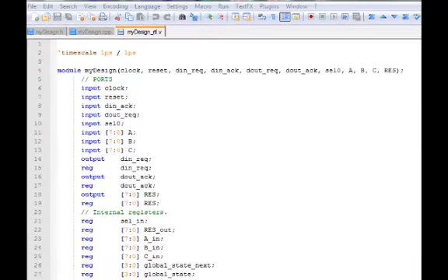So let's take a look at the Verilog code we might write to implement our tiny example. For the moment, let's restrict our focus to the definition of the module itself, as well as the ports and internal variables. Here we see the Verilog keyword module, followed by the user-defined name of the module. In the parentheses, we have a list of all the port names. Next, we see a list of the port definitions. Each one includes the direction of the port, the name of the port, and optionally, some specification of the width of the port. The internal variables are all defined using the reg keyword in this case, and includes the variable name as well as an optional width specification.